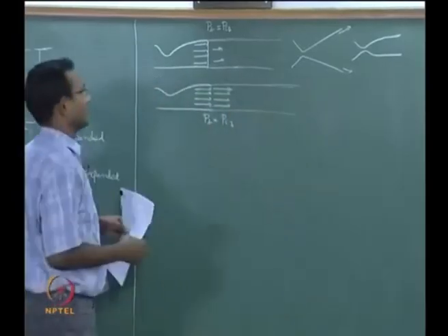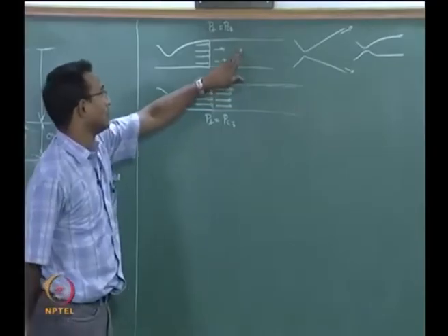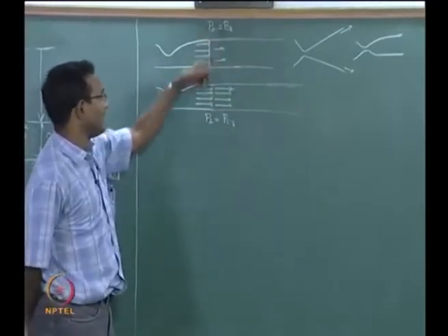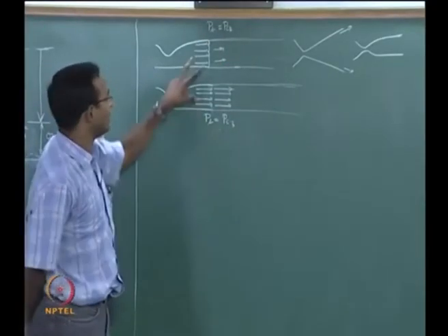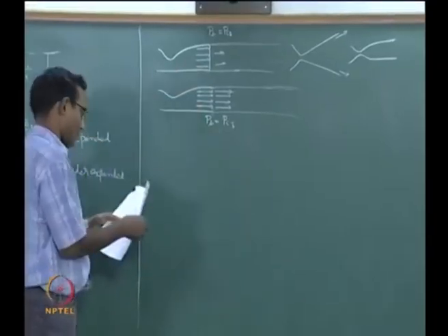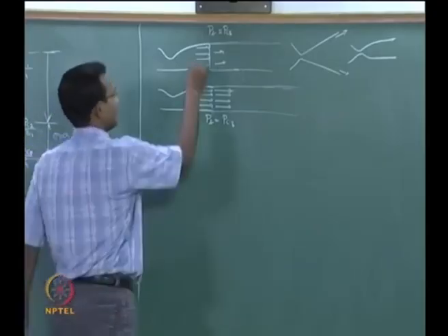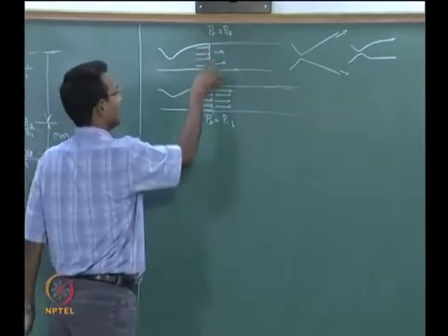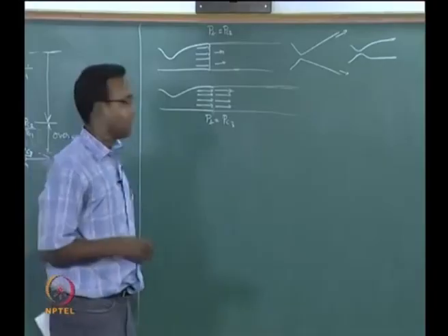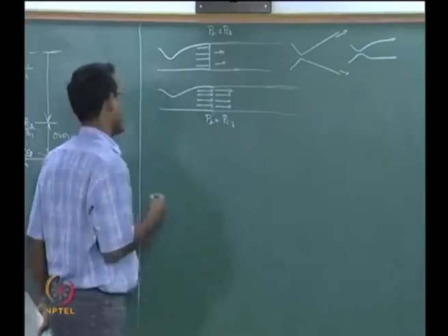So, if I look at this, I have this at P critical 2, and when I decrease the PB to P critical 3, in between, what happens is our discussion for now. What should happen? Here the pressure is low, across the shock pressure becomes high. We said this flow is over expanded.